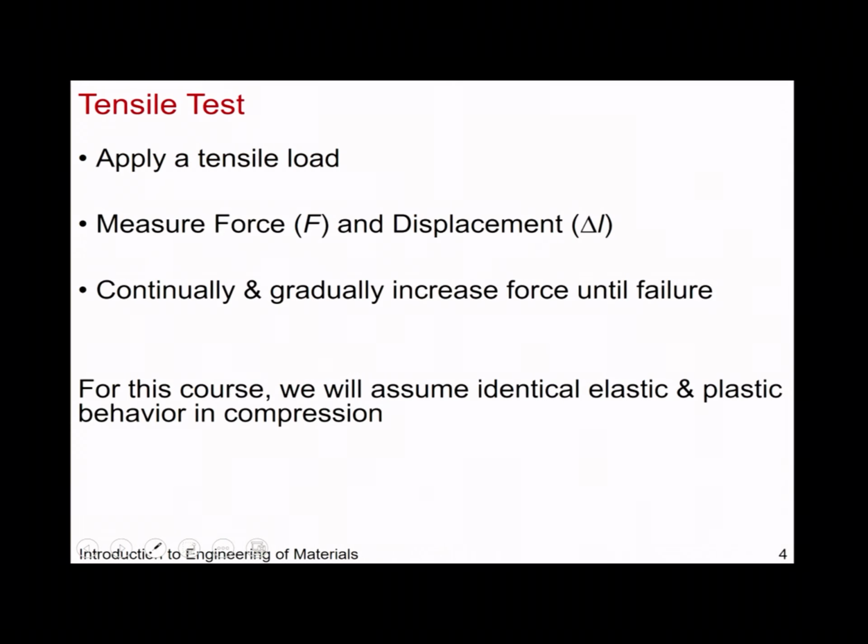Okay, so when we talk about stress states, how do we do these experiments? Some of you may have taken a lab where you've already implemented this, but if you have not, the way you would do it is you can apply a load or some sort of force in tension, in compression, in an idealistic world. You can measure the force, because you know that, and then you can measure the displacement as well. Both of that information will give you data on the stress strain curve of the material, and you just basically keep applying this load until your material fails.